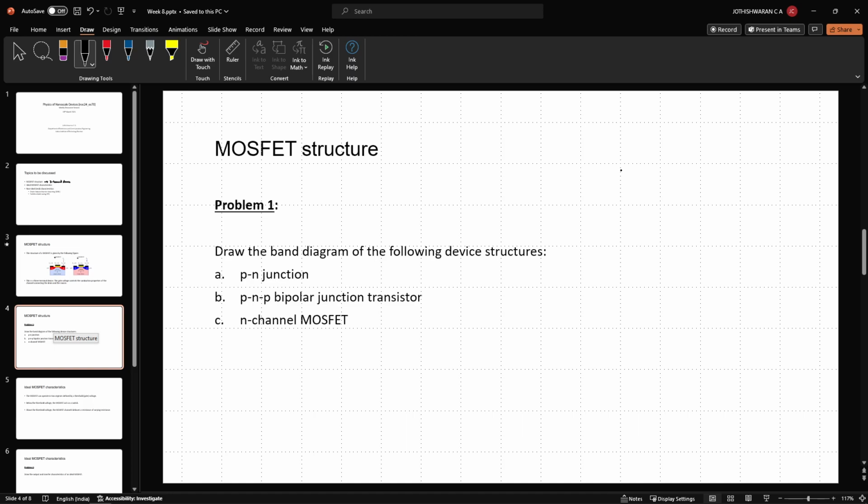Of course, everybody who has studied a semiconductor device course or any kind of introduction to electronics course will know that a band diagram typically moves along one position coordinate. So if I have several materials placed in junction with each other, we move along this axis and say where the conduction and the valence band lie in the respective materials, and what will happen when these materials are brought together under equilibrium conditions.